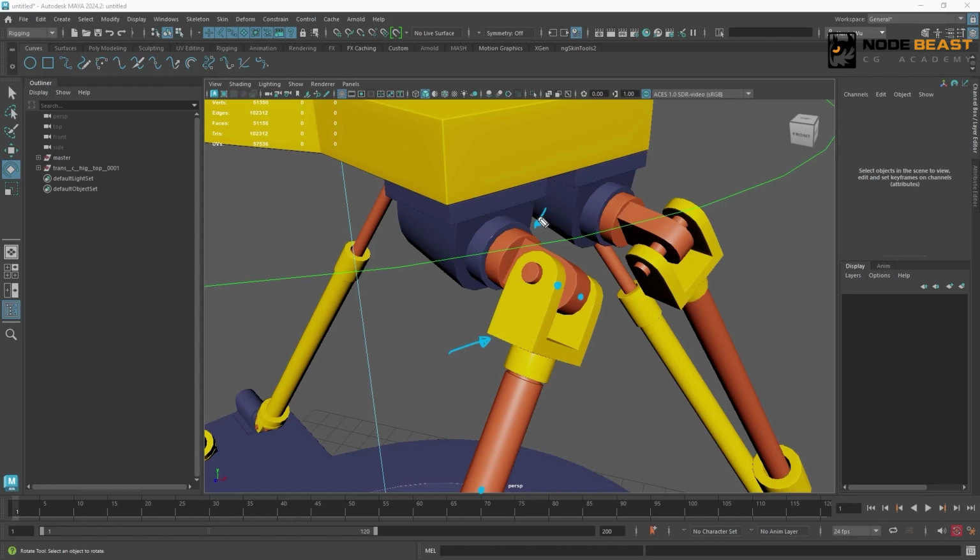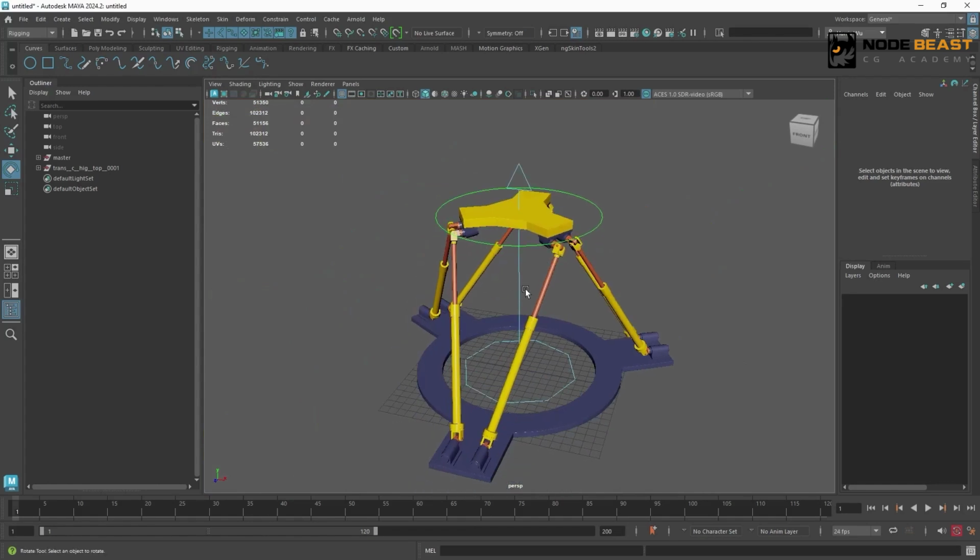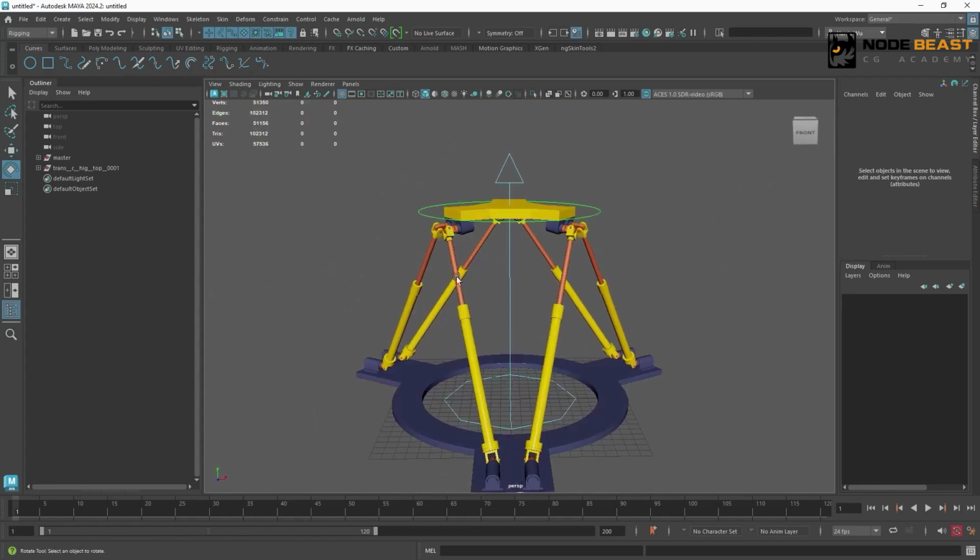Next is our base, its rotation center. We can look at its structure. It's a cylinder, so it's the center point of this cylinder. Where is its aim constraint driver object's position? We know this base is always pointing forward, so its driver object's point is actually the up reference point from the previous part, and its up reference object's point was driving its rotation. It's driven by our upper part, so its up reference object's point is actually the driver point from our upper part. This way, if we look at this one section of our model, it has 6 sections.